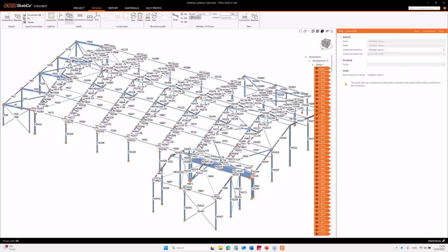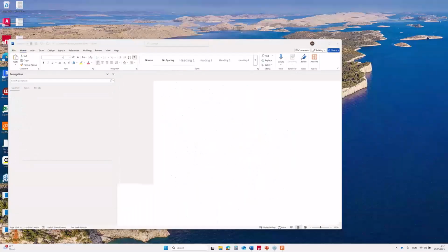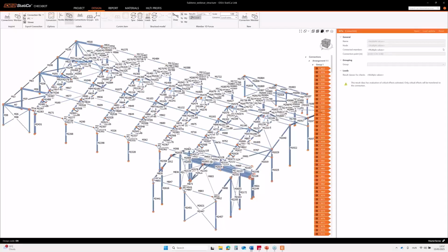Okay, there is another question on class 4 cross sections. Can you handle class 4 cross sections as well? Class 4, yes, we can handle. The important thing to recognize with class 4 is their susceptibility to local buckling, which is why I mentioned buckling at the beginning of my part within this webinar. It's an important feature of those thin-walled sections.